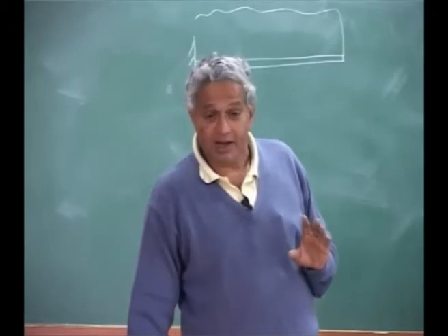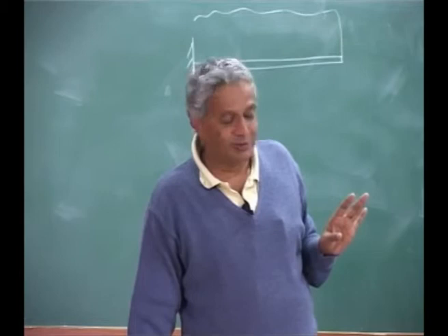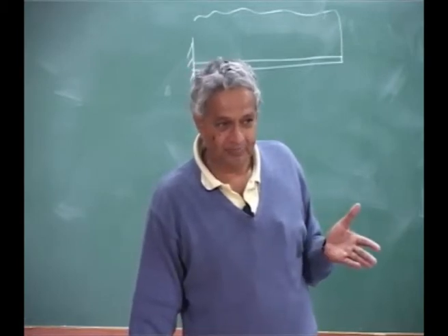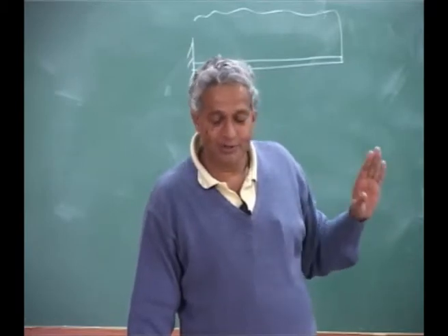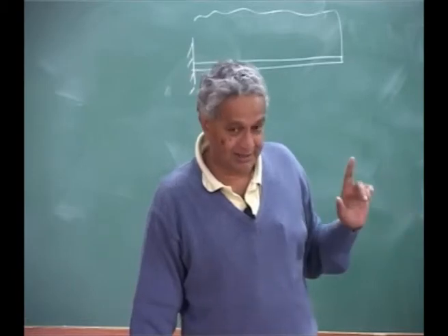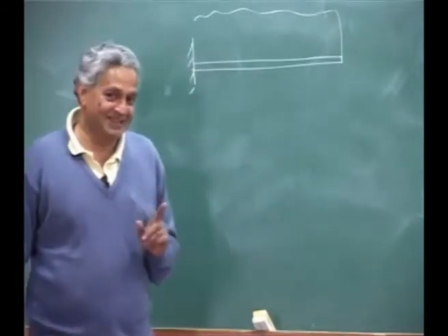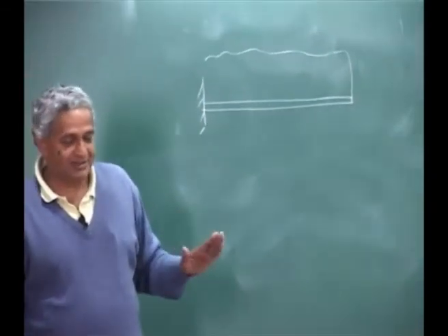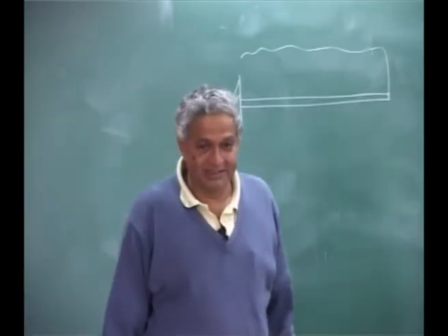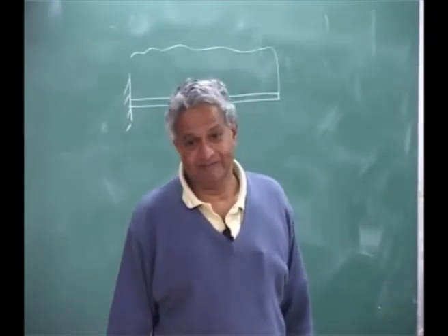But if it is not self-adjoint, then these two will not be the same, in which case you directly go and use the Galerkin method, not Rayleigh. You go and use the Galerkin technique for a wing divergence of a swept configuration, because you derive the equation and then apply the Galerkin technique.